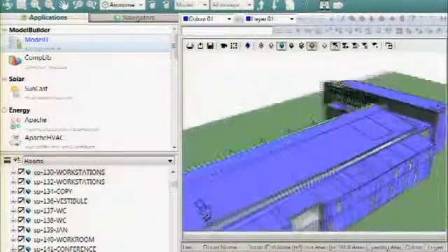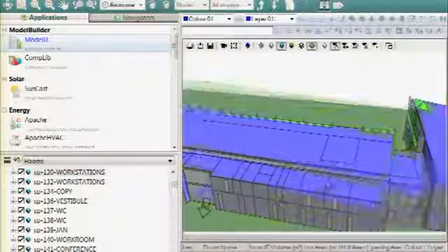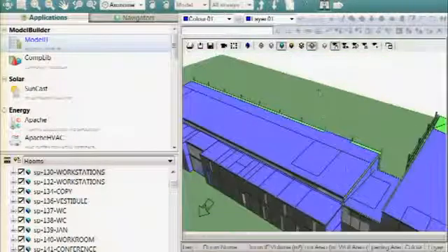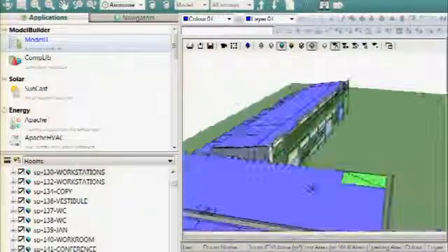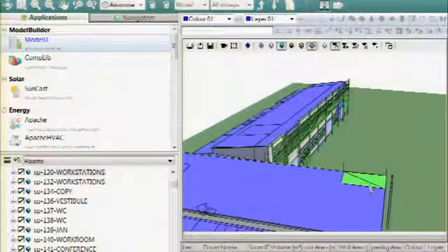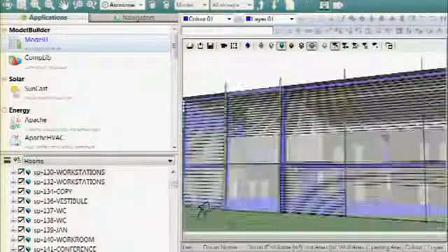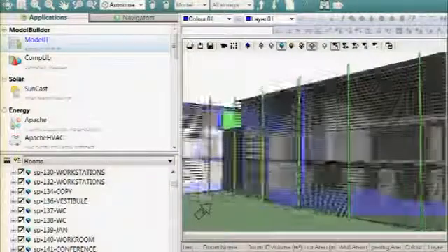VE. So you can see that some of the issues with this model is you'll still have some shading surfaces sometimes peeking through that need to be fixed, or this right here is a direct result of the healing tool, where it actually comes together and will fill in a space rather than leaving a gap between the planes, which is good when you're looking at daylight. But this is the type of shading you want.